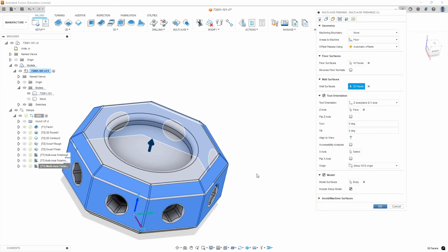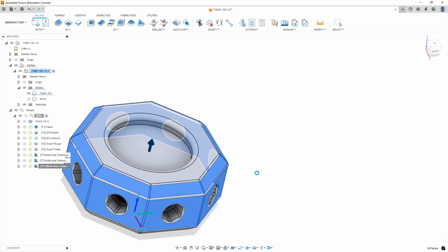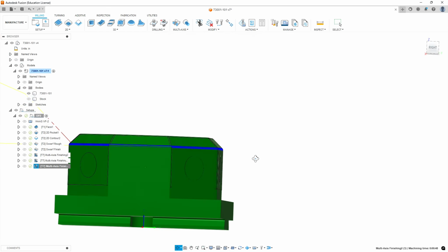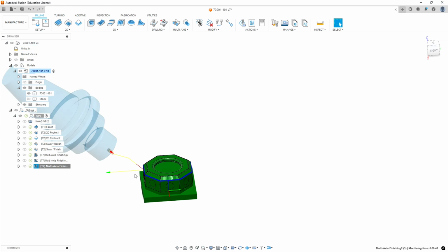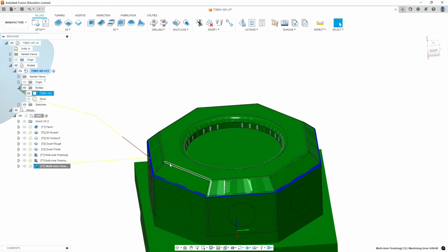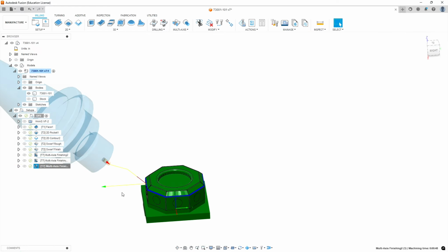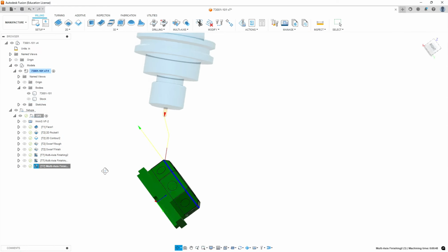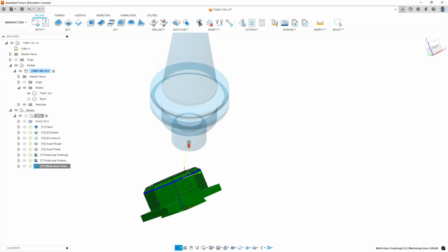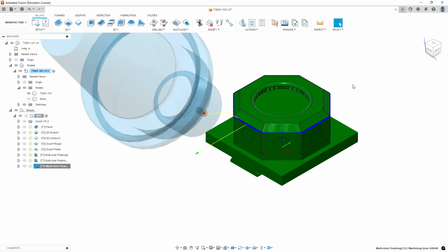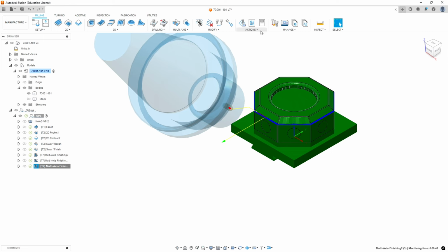Okay. I'm going to select OK, keep everything else at default, and see what happens. Remember, this one we set for conventional cutting too, so it enters and then it goes around in a circle. This one doesn't do those individual cuts, so maybe it has to do with the angle, the top being first cuts being normal to the standard spindle direction. All right, it looks like it rolled over the sides just fine.